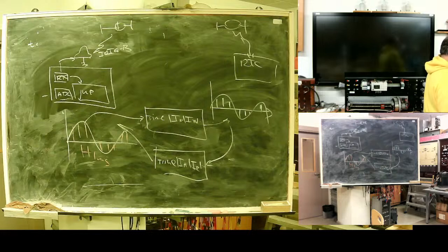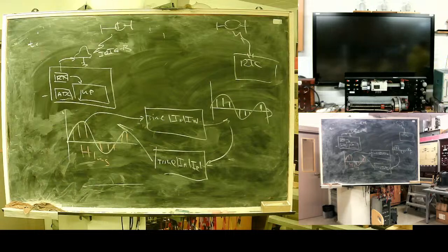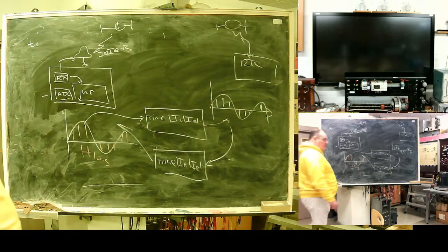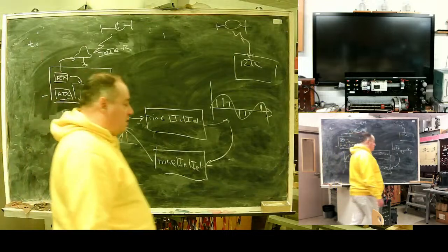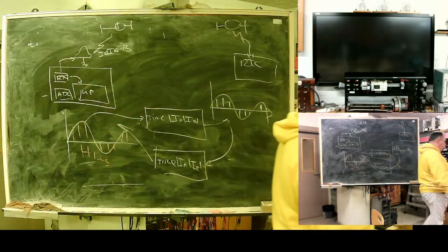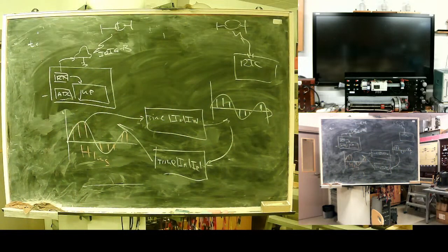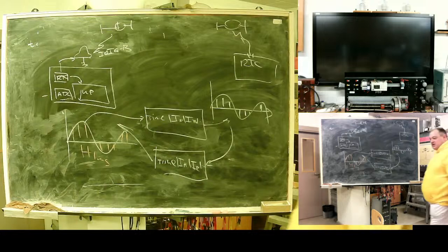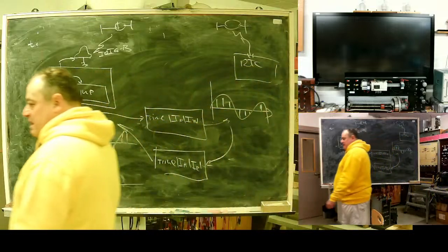If the data synchro channel cannot be established, it's a mandatory thing. The line protection terminal falls back to distance protection mode. We cannot be 100% sure what timing source will be available, and what data channel will be available.